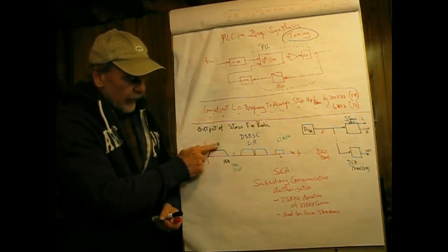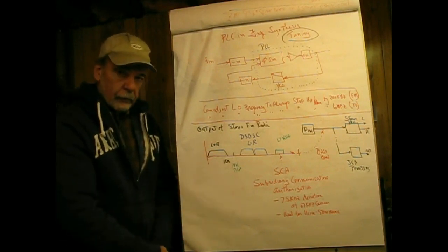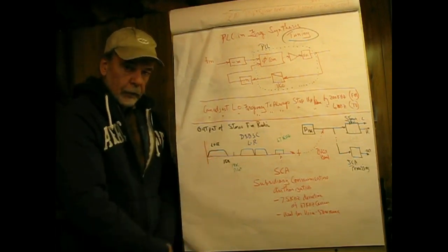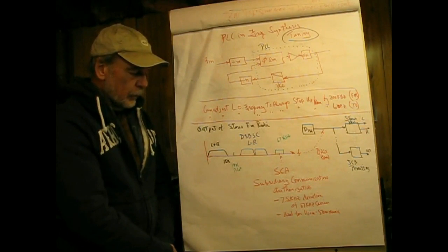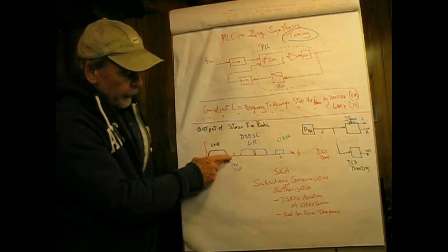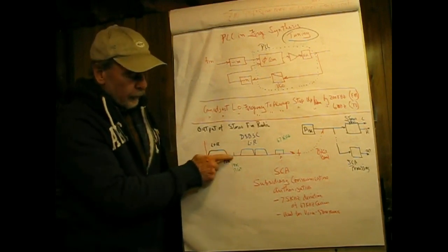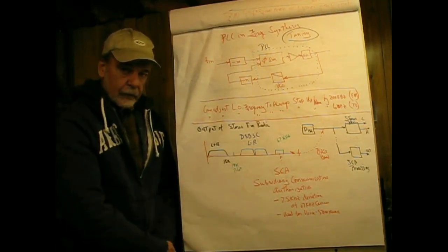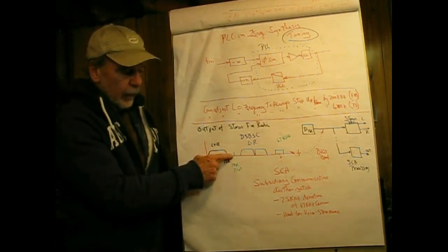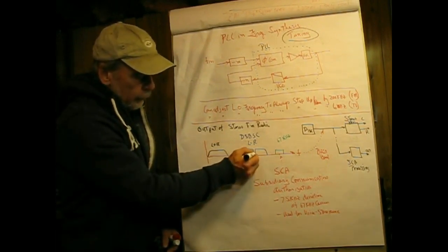In the beginning, we have a left plus right signal, which simply means that the left and right are added together. You can do that with 3 resistors. It's a linear addition, and this would be the monophonic component, so that non-stereo radios can receive standard broadcasts. Also sitting up here, we have a 19 kilohertz pilot. That's very important, and that does 2 things. First, it turns on the stereo light on your receiver, which on larger ones they have, and secondly, if we take this and double it, it's 38 kilohertz, and it becomes the carrier for this guy.